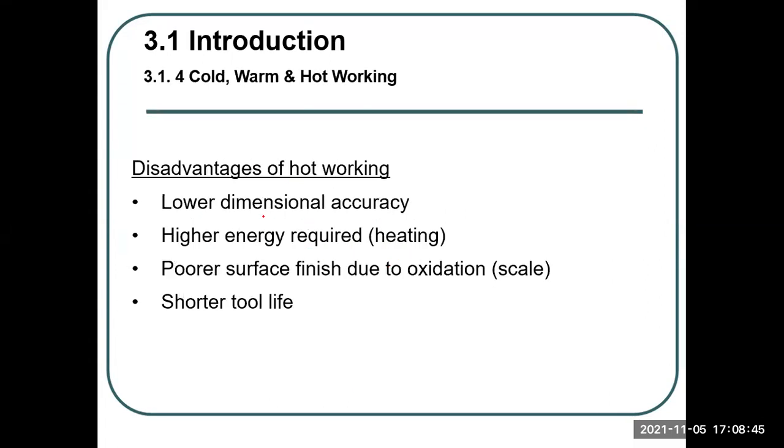The disadvantages: because you need to cool down, there will be shrinkage, so it's more difficult to control the dimensions. There's higher energy because you need to heat up. There's poor surface finish because you might have a lot of oxidation and scales. And the tool life might be shortened because of the heat.